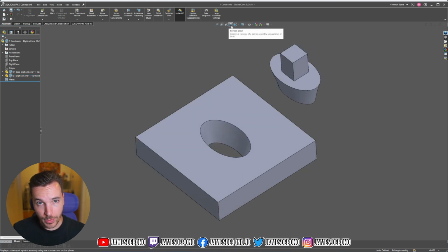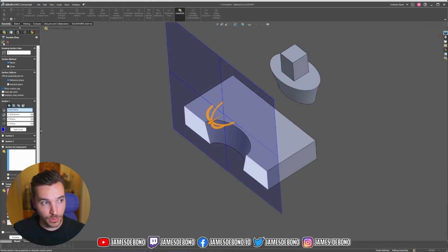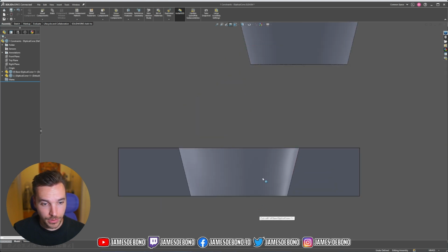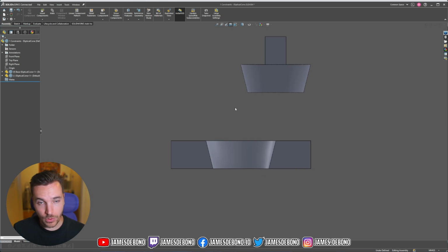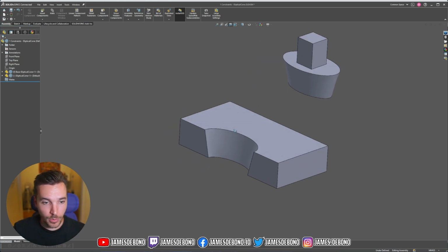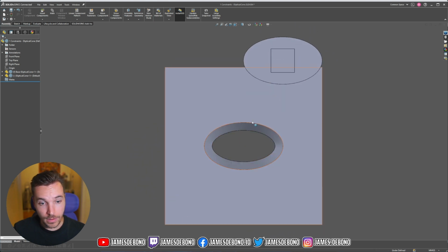Now the hole in this plate, if we look at the section view, is actually conical. So it's like our countersunk screw where it's cone shaped, which automatically allows us to reduce 2 mates down to 1. But the other unique thing about this hole is that it's an elliptical shape. Now, technically, an ellipse mated to an ellipse would prevent it from rotating, because this face would be fixed either in one position or the exact 180 rotation of that.